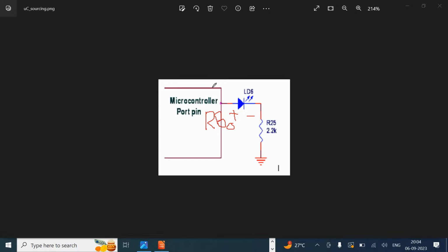Don't you think this microcontroller, via this port pin RB0, is giving a signal out to the peripheral LED? Either 1 or 0, it is giving out to the LED peripheral. If I'm putting 1 here, it is going to be input to the LED, and the LED will glow and current will flow, right? So the microcontroller is giving something outside. Agree? So what will be the pin direction? If it is going out as input to the external peripherals, then the pin direction is going to be an output pin.